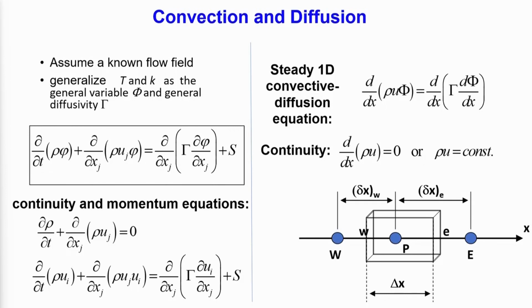The question is how do you know what the velocity is, because let us say you are solving the energy equation where the convective transport of heat is taking place. So, what does it mean? That you have a change in temperature where the fluid velocity also plays a role. So, if you are trying to solve for temperature from such an equation, you have to substitute the value of velocity, only then you can solve for temperature in that equation. So, the question is where that velocity will come from.